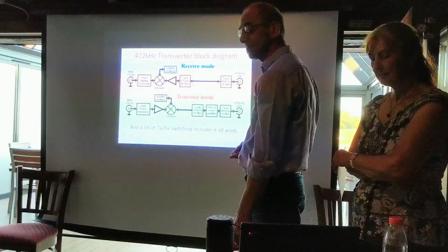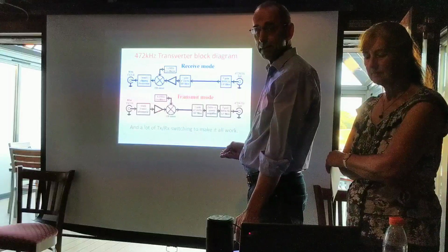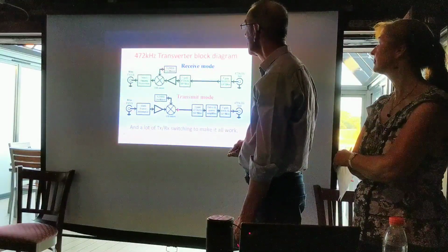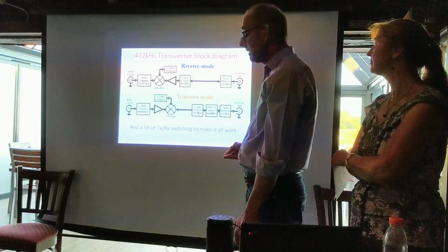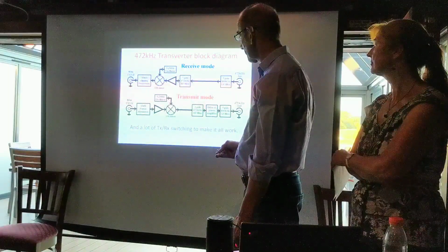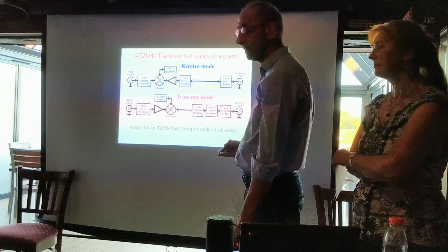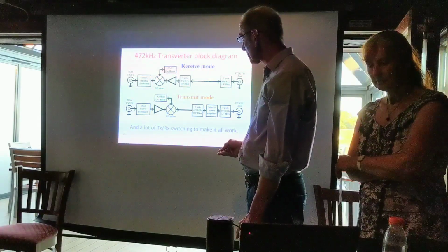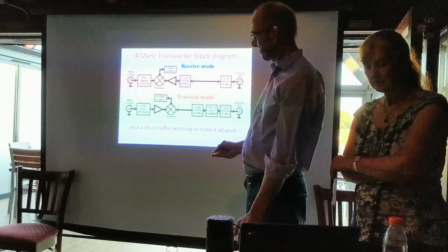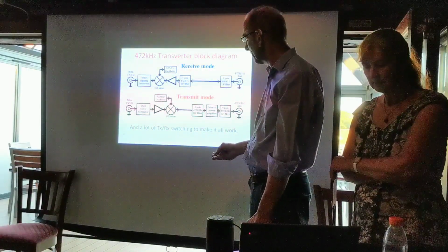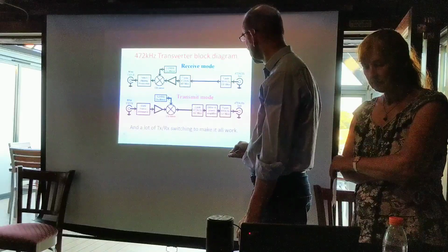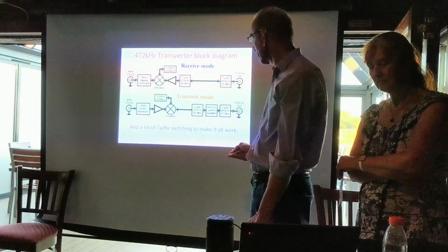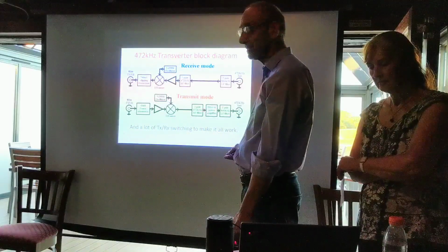Again, this is a double balanced mixer, so we only get the sum and the difference out, the other two bits have gone. But we need a filter here because there will be a different signal here. So we'll get the 80 meter band, 3.6 megahertz minus the 3.2 will give us the 400 we want. But of course there'll also be a signal which is at 6 point something megahertz, which is the sum of 3.6 and 3.2. So we need a filter to get rid of that because we don't want to be amplifying that and using up a lot of power to do it.